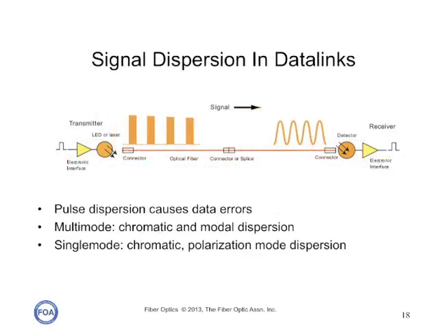The second problem we have in signal transmission is dispersion, that an optical signal gets spread out by the characteristics of the optical fiber that's transmitting it. We must ensure that for every data link that the signal at the receiver is such that each individual pulse can be distinguished by the detector in order for the signal to be transmitted properly. Dispersion is a problem in short multi-mode links and very long single-mode links.